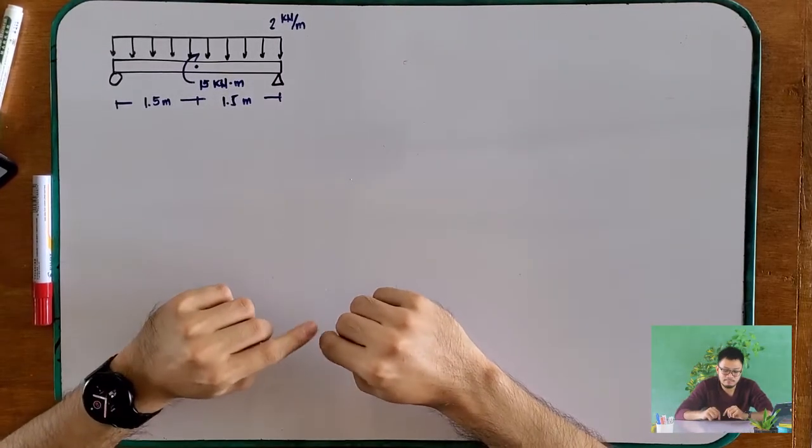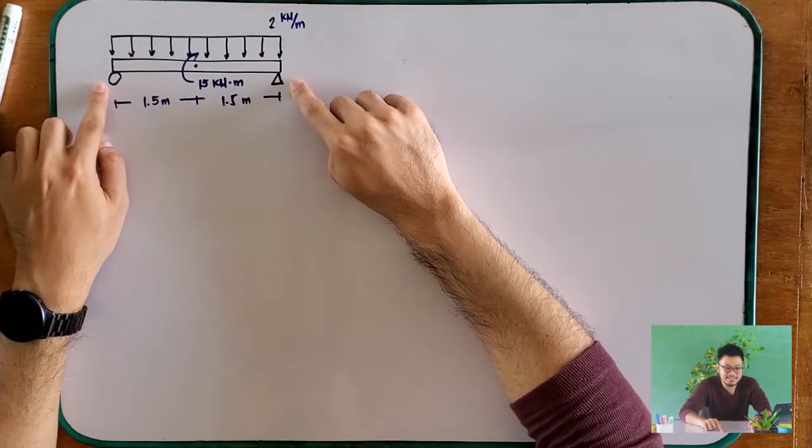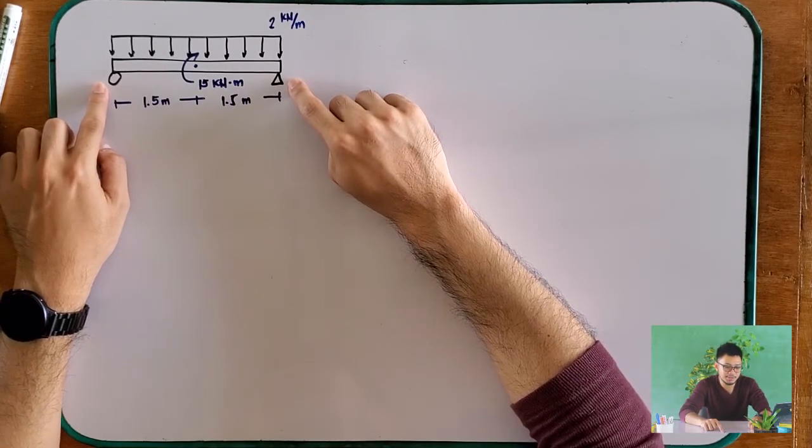So what is the first thing to do? The most important is that you should account for all the external forces. But in here, it is not really necessary to solve for the two external forces or the support reactions, because with the method you will use, you are just going to cut the beam, and you can leave out either side, whichever side you choose.